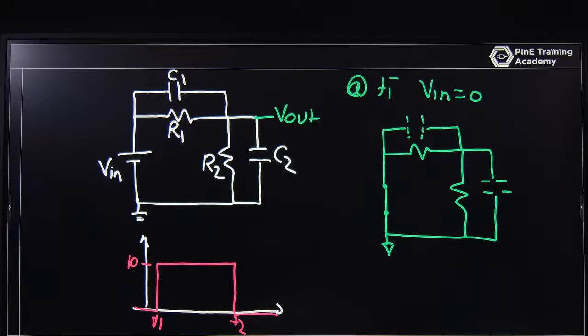That's why I am saying that I is equal to V by R, so there is no problem. You just find the resistance and voltage and you can determine what the current will be. But in a capacitor, whenever you talk about the steady state, or DC state, or constant state, the current is always 0. That's why I am saying the capacitor acts like an open circuit, because the current is 0.